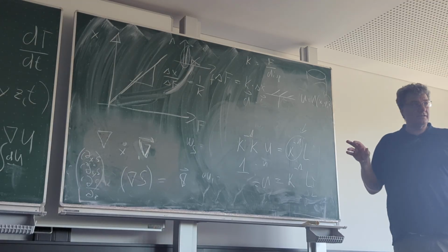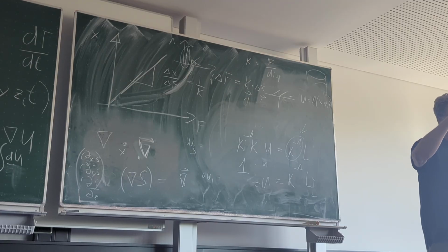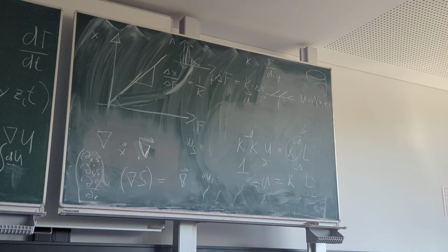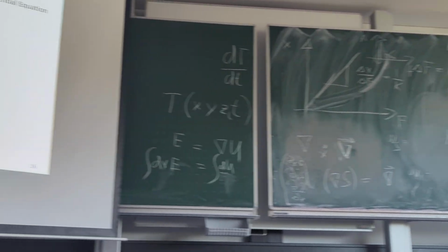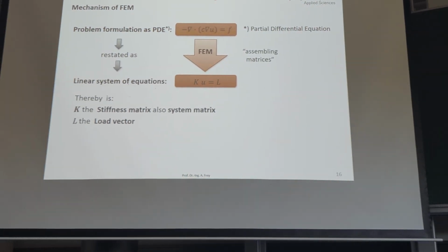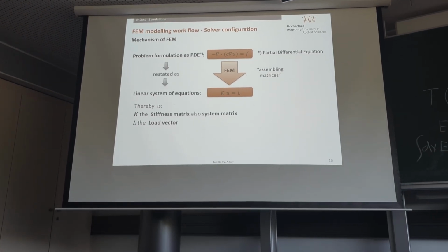Even if the 2D is not the complete truth and you have to modify it later, you already get some idea what the effects are, where there is a lot of mechanical stress, where it's not so much. And then later you switch to another method. The general idea is to start simple. Maybe not all physics impacts: you start with one, solid mechanics, later you take temperature, and later you add current, and so on, so you make it more and more complete step by step.